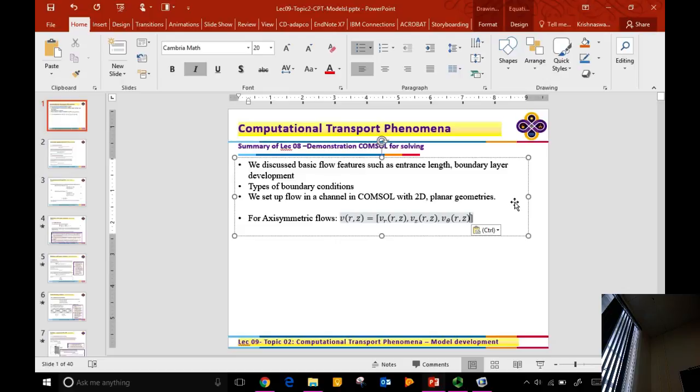This is axisymmetry, this is all solid, and that's all solid. And this is inlet, and that is outlet, right? All you have to do is, if you rotate that around that axis, you're going to get a sphere in the middle and a pipe surrounding it. So you will pick, once again, 2D axisymmetric mode and build that geometry. Okay? Is that clear?